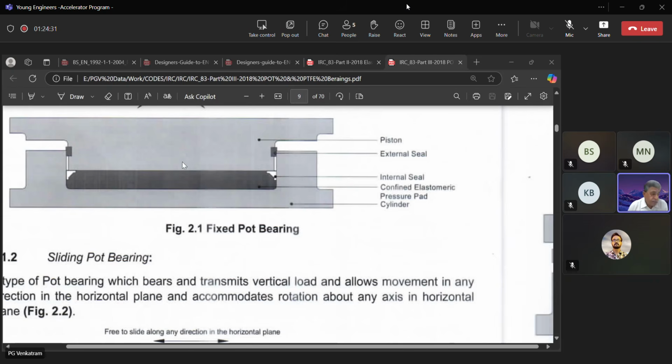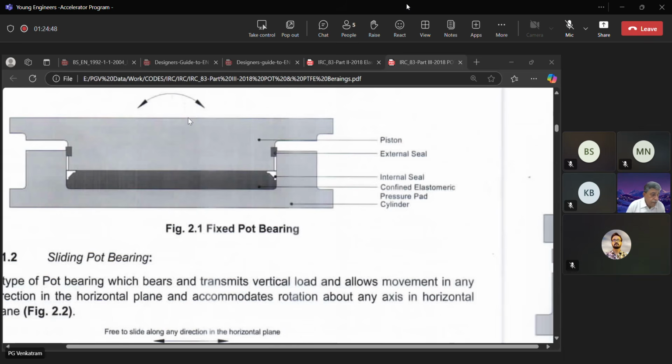And of course, at the top. I'm not denying that, but the top is less important because the elastomer will not expand; it will only confine. And not only that, because the piston is much thicker than the base, its rotation is very unlikely, even if the grout quality is bad. So that is the reason why you need good quality grouting for this, as opposed to elastomeric bearings.